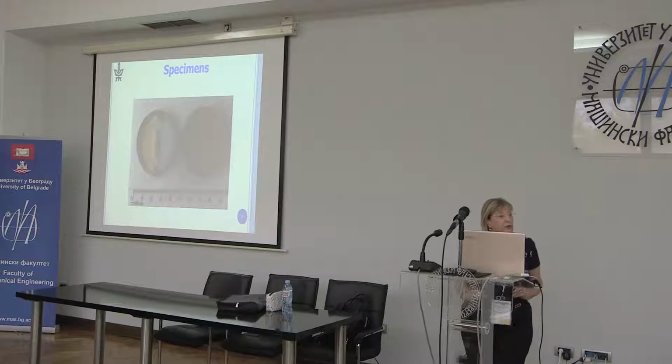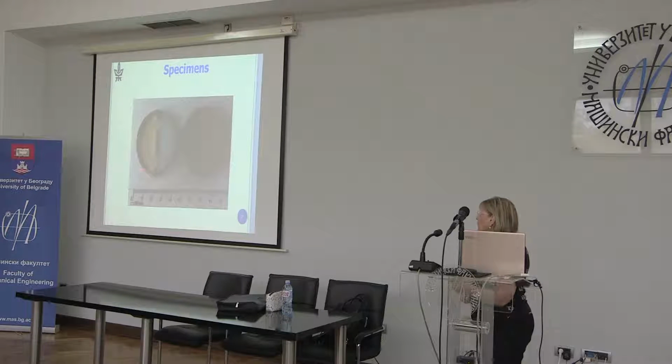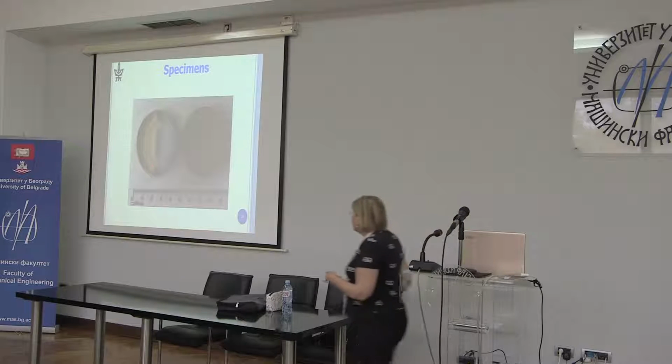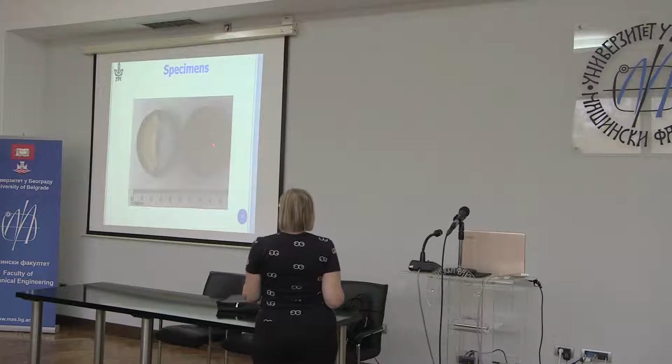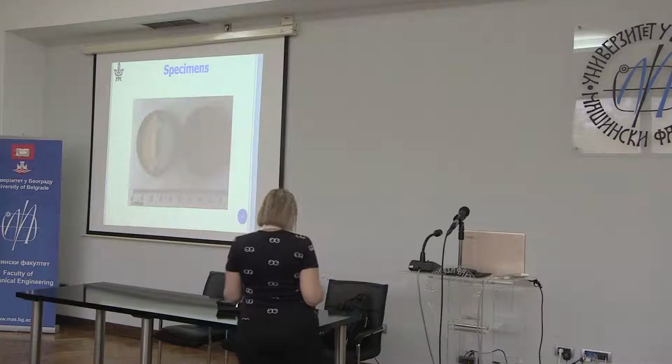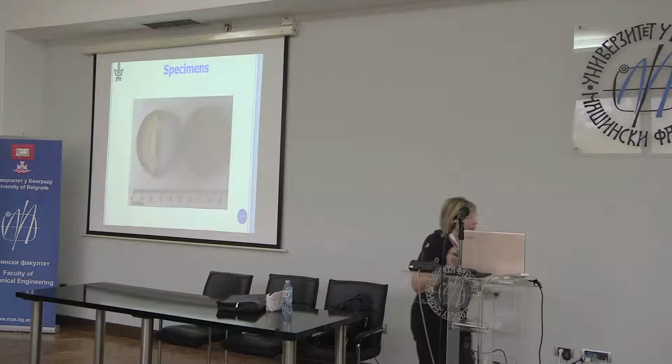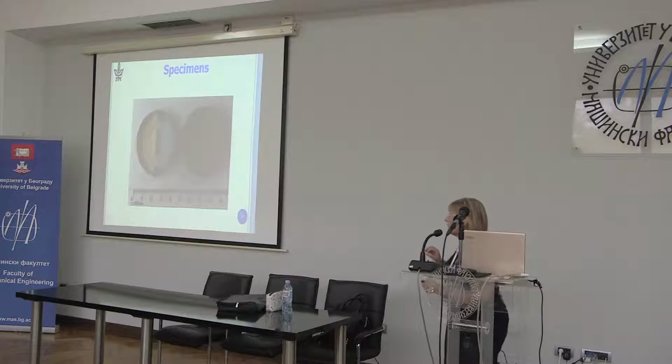And now I would like to tell you about tests. These are Brazilian disc specimens, and I'll explain them further. The diameter of the specimens is 40 millimeters. We have an interface crack. I can't see anything here. I guess you can't see anything here too. On my computer, I can see I have two different materials, and there's a notch here created by Teflon, which is about 25 microns thick. And here we had Teflon, but we induced a natural crack there.